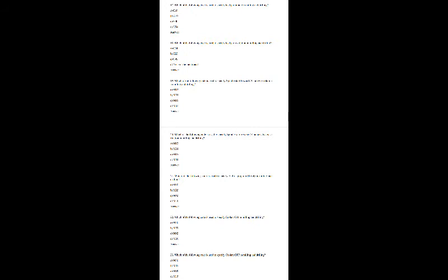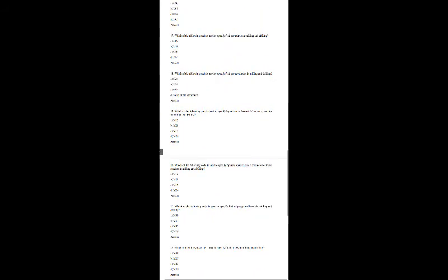So here the correct answer is option C G95. Okay, in our part programming examples for milling and drilling we have seen the feed, that is feed per minute and feed per revolution, and we have used these codes G94 and G95. Okay, now let us see the next question.